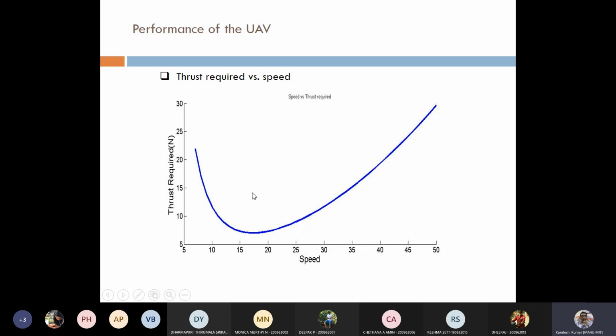But we talk about 70%: at least you should have 70% thrust. If you want to take up a 10 kg aircraft, then at least 6 or 7 kg of thrust you can get from the propulsion system, either electric or engine. You have to look at that. If you have a very high thrust propulsion system available, that is fine, that can take care of the drag, correct? But is it supporting the flying or not? So you should have at least an analysis over this also.